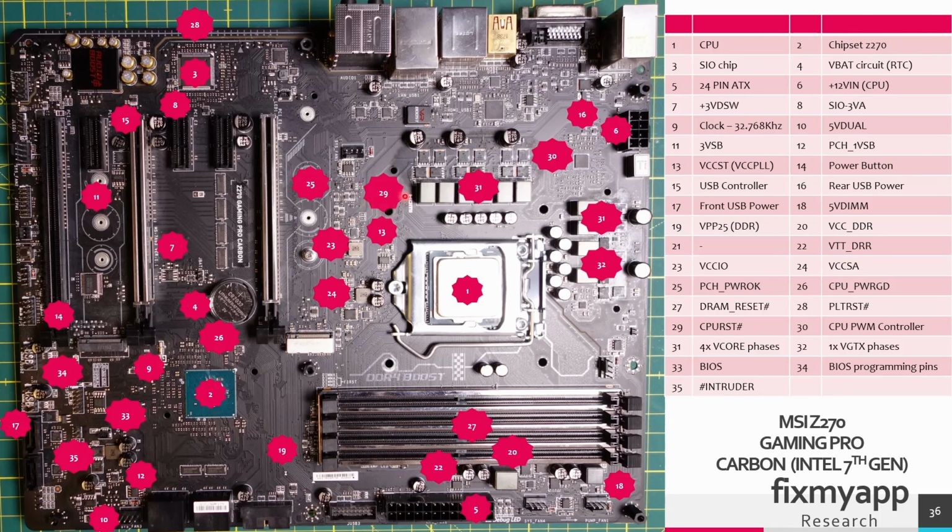In area 29 we can find the CPU reset active low signal. When the CPU reset signal is pulled low, it forces the CPU into a reset state, actively stopping its current operation and clearing any internal states or registers. This ensures that the CPU starts executing from a known state once the reset is deasserted, so the signal goes back high.